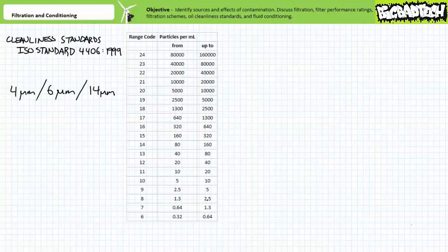For applications necessitating extreme cleanliness, it makes sense to start with the cleanest oil available, whereas those applications not necessitating extreme cleanliness can get by with a cheaper, less clean oil. Hydraulic oil ISO cleanliness standards are communicated using a 3-number code, sometimes 2, where each number in the code represents a range of particles of a given size per unit volume.